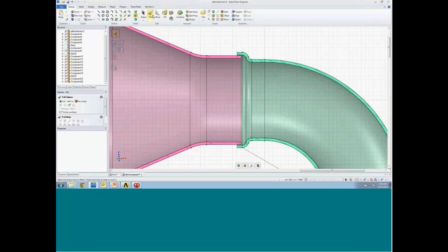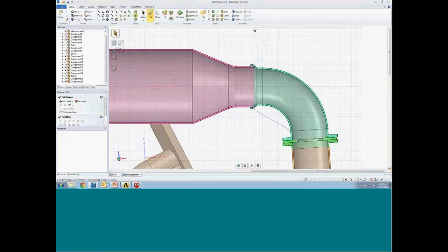So what I've done is open this up, and I've cut it in half. I've gone into a cross-section mode. The great thing about looking at things in a cross-section mode in SCDM is that it's not just good for visualization anywhere you want, but you have full editing capabilities too. So this catalytic reduction chamber, I take the very end of that, pull on it, and create a definite interference between itself and the green body. And I'm done right there.